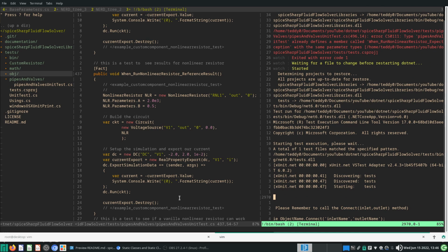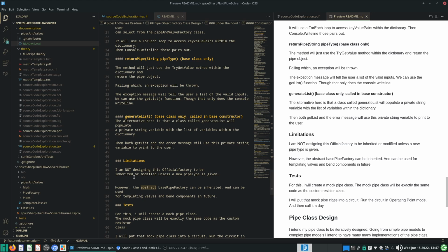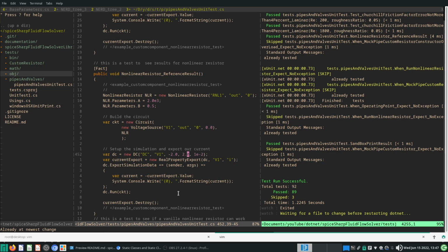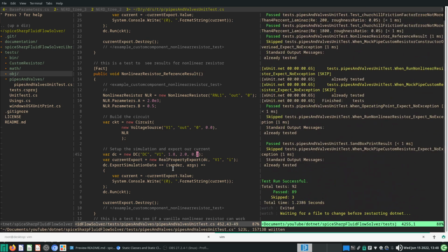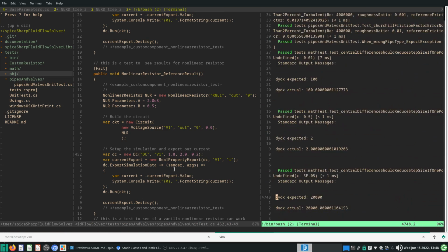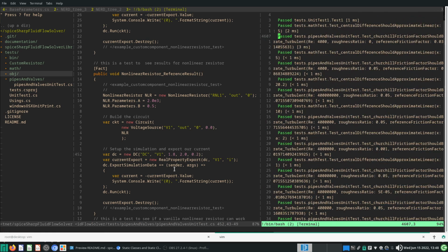Okay, hold on. Let me sort this out, and then I'll come back to you. Since this thing is actually printing out so much, I want to change the voltage here to be from 1.8 to 2. So the voltage sweep will be from 1.8 to 2 in steps of 0.02 or 0.2, so I don't print out so much data. Let's see what the data is being given.